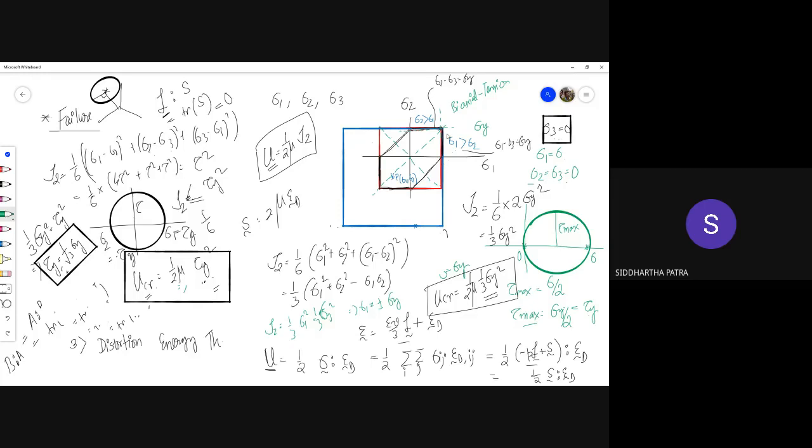If you take even sigma 1 equals sigma 2, you see it is again sigma 1 squared, so again the values of both quantities must be plus or minus sigma y. So all of these points, all those coordinates, are part of the distortion energy theory. So this is what the distortion energy theory would look like: this ellipse right here.